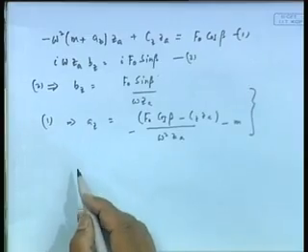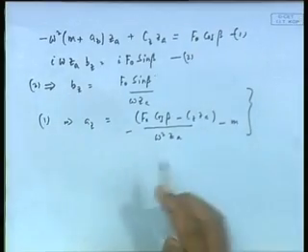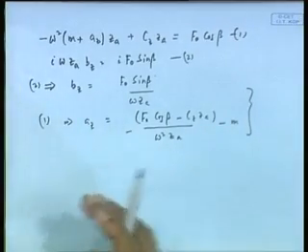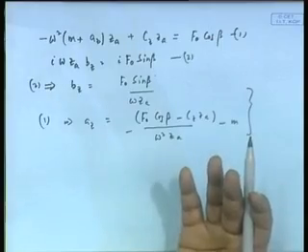Why I mention this now in the class is because usually this is not so commonly known to people. Many tests you do for design purposes directly find the output, but here you are finding added mass. Added mass is just a quantity which would be useful tomorrow if you want to predict ship motions, but you are not measuring ship motion directly, remember. Like resistance you are measuring directly, so many kilonewton is the total resistance.